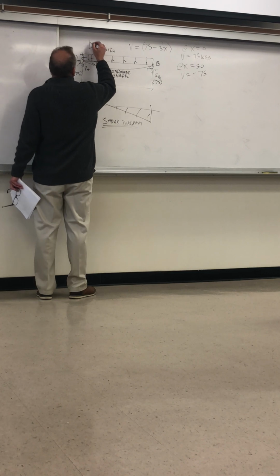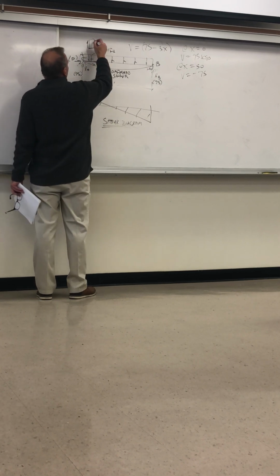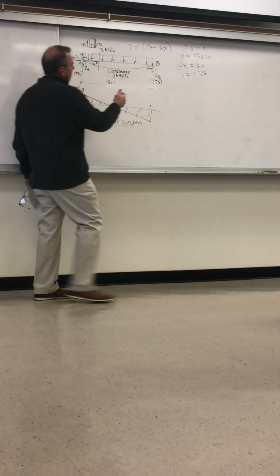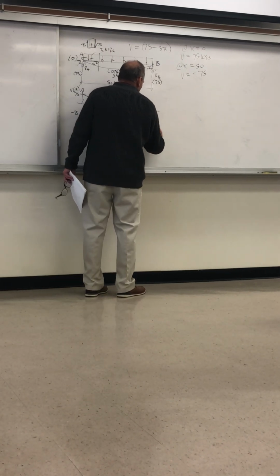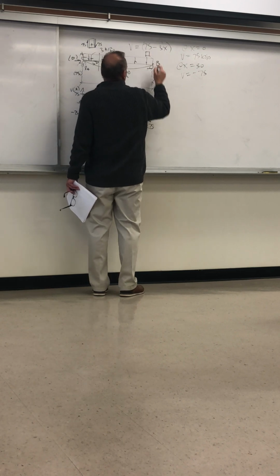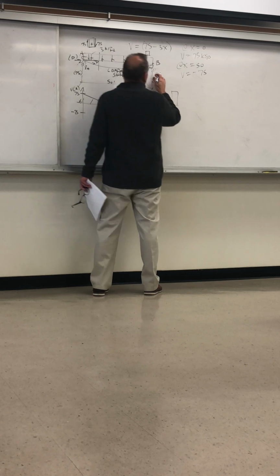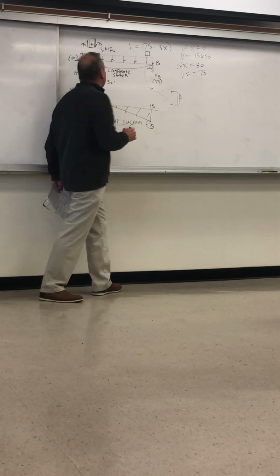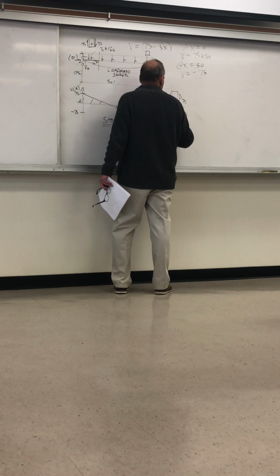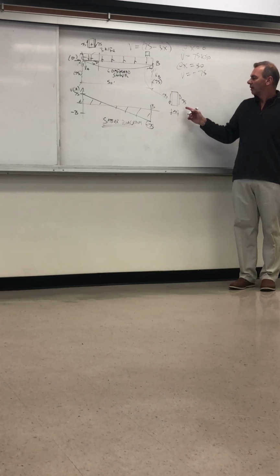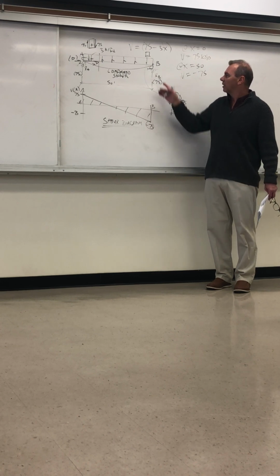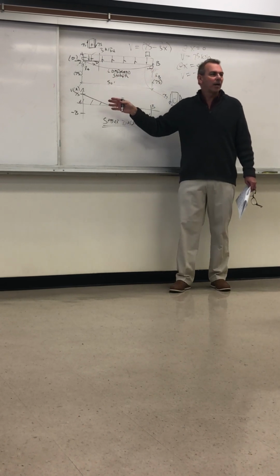So you can see at the beginning, if we take out a little segment, this 75 up has to be 75 down. This is clearly positive shear. That's why it starts as positive. If you look at the right side, over here, notice this is minus 75, right, at B. This is A. And if you take a slice here, and then draw it over here, you see on the right, there's 75 kips like this, and it has to be 75 down. This is a differential segment, so they have to be balanced. And this is opposite to that, so this is a negative shear. And that's why this is a minus 75 there. So we could have just gone straight to here and said, oh, it's minus 75. Because it's a distributed load, the shear diagram is going to be a linear variation.